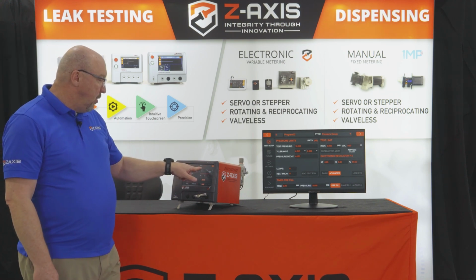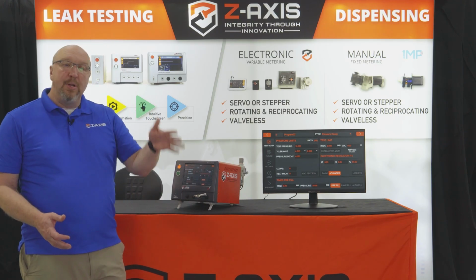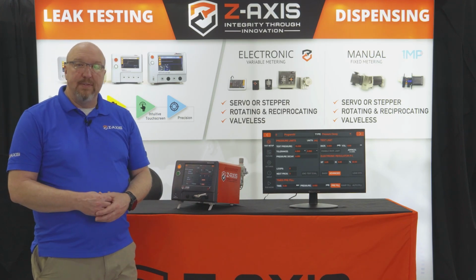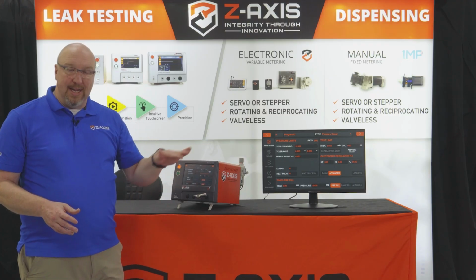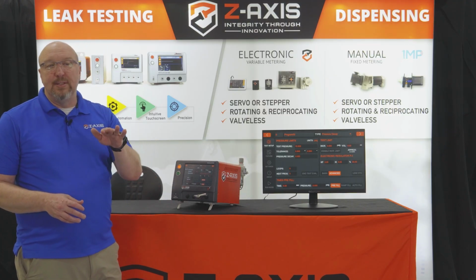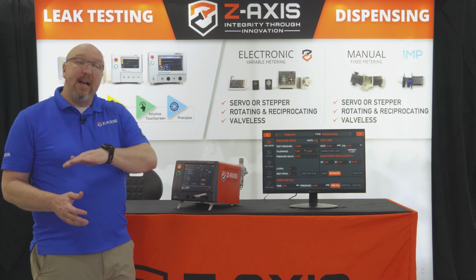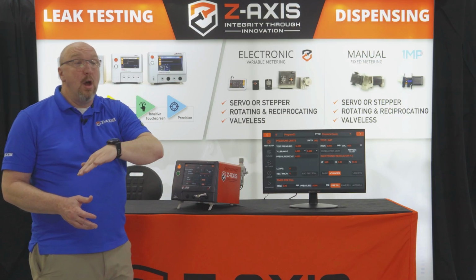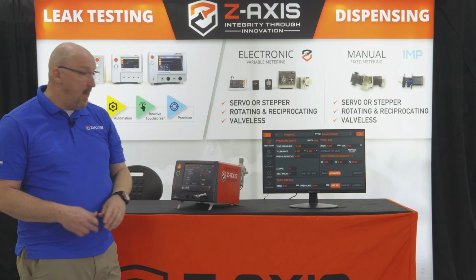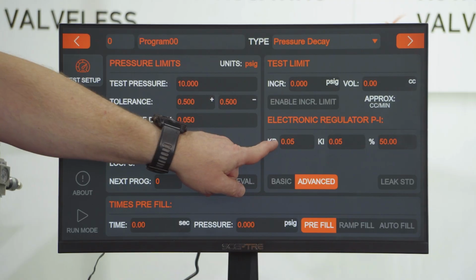So there are controls on the electronic regulator to allow you to tune the fill curve of that. We have some customers that don't want a stair step of pressure hitting their part. They want a nice smooth transition. And so we allow you to change some control feedbacks to make a nice smooth fill or a stair step kind of a function. That would be right here for the electronic regulator controls.